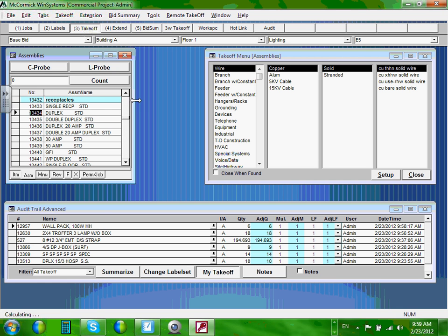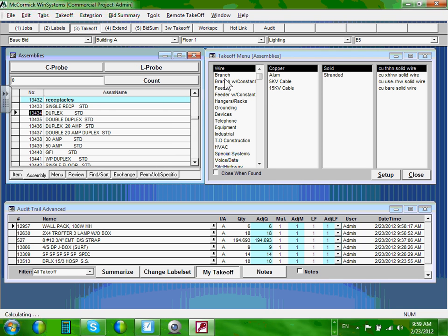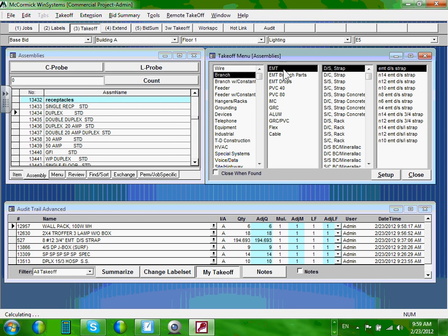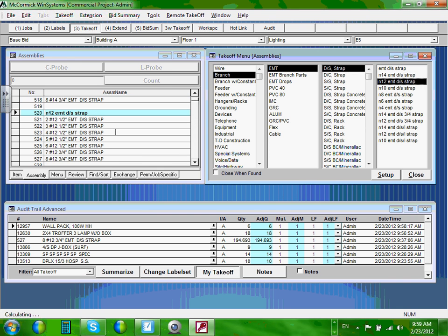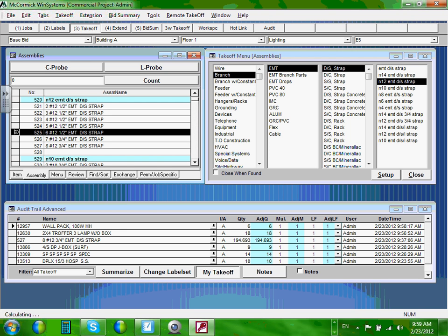Okay, I'm going to take under lighting fixture, the same thing, branch circuits. And I'm going to use EMT, same strap, number 12. This time, all these fixtures, I fit them with the 6 number 12 in 1/2 inch EMT conduit. Now, if you are putting it in a 3/4 inch, then you can take them as wires and conduit, separate. Okay? So I grab this. Everybody's there, guys? Branch circuit, EMT, number 12, and right at 6.